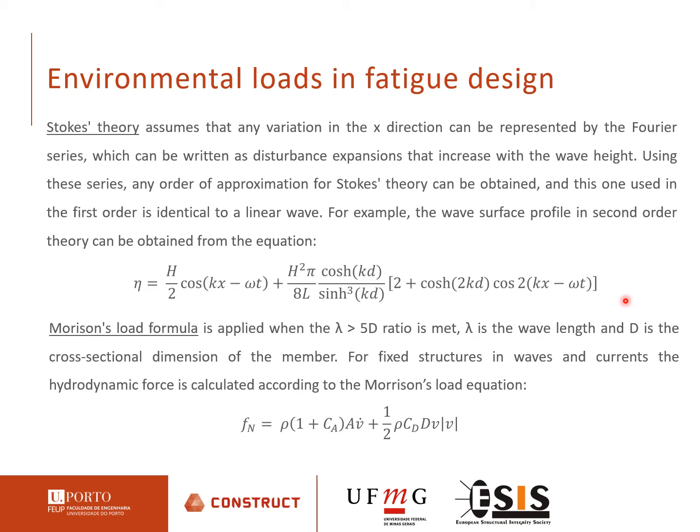Morison's load formula is applied when the wave length is 5 times bigger than the cross-sectional dimension of the member. For fixed structures in waves and currents, the hydrodynamic force is calculated according to Morison's load equation.